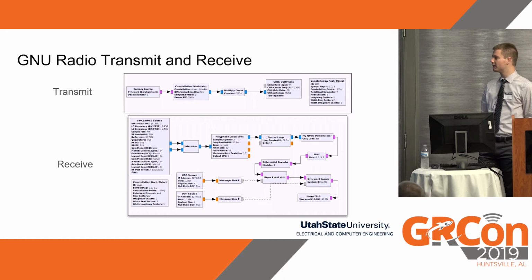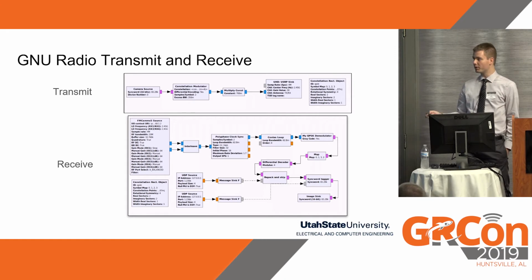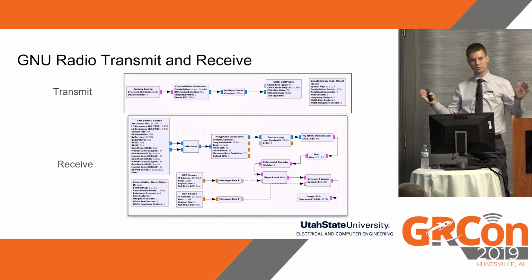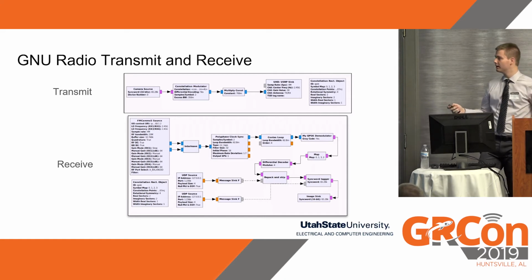Normally you have two different channels here, independent channels. But what this is actually sending out is interleaved samples from the coherent wideband signal that's been reconstructed in the firmware. And the reason for that is because, of course, since you have double the bandwidth, you've got double the sample rate, twice as many samples. So the way we handled that was just interleaving those samples between two of the channels.